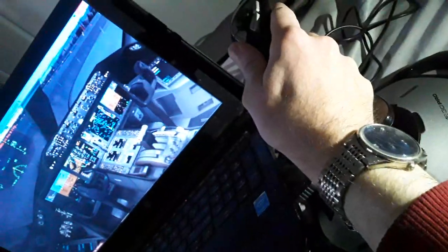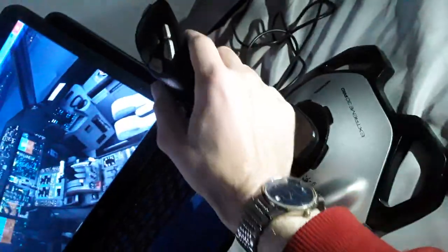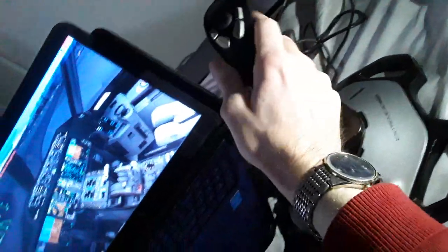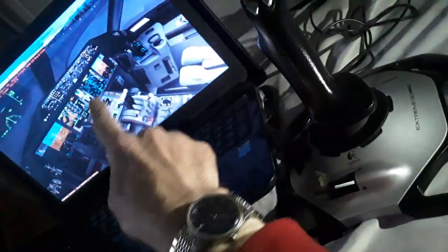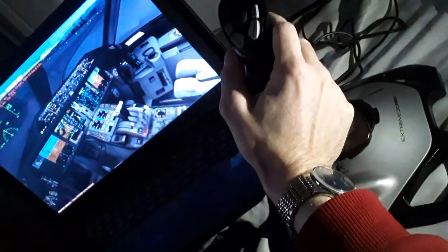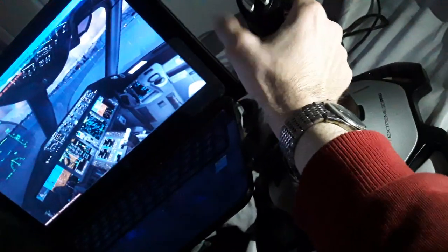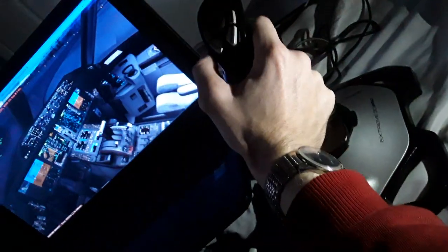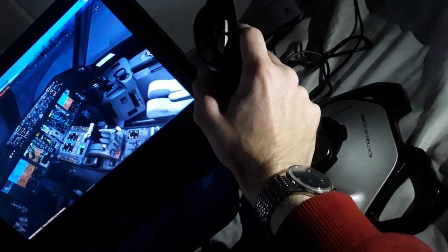So you can see the side stick deflection is proportional over here to the yoke deflection, as you can see. Also the captain and the first officer are moving together, they're interconnected in flight. All flight controls move simultaneously together unless you have a failure, you want to override with a force one side by another.